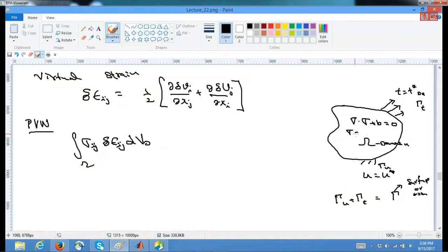And we have mentioned u here, traction somewhere here, and then we are saying that sigma equals, in terms of the initial notation, Hooke's law can be written as sigma equals c epsilon, or in the other notation, our constitutive law is sigma equals D times epsilon. It is a similar relationship written in a different style. This is in a tensorial form and this is in a vectorial form.